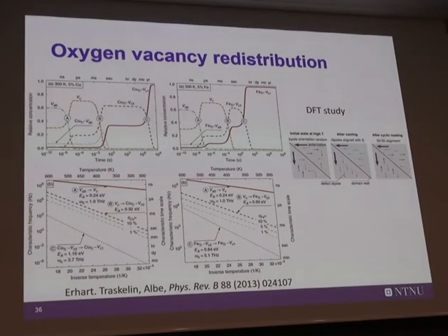But then the next thing happening, at a longer time scale, is the trapping of the oxygen vacancy. They're trapped by the acceptor dopant, and then you end up with this complex point defect pair, which influences the ferroelectric properties. So by doing all the energetics and all the kinetics, they are able to track down the relaxation time for going from a random distribution of point defects to the specific pairs which lock in the polarization.